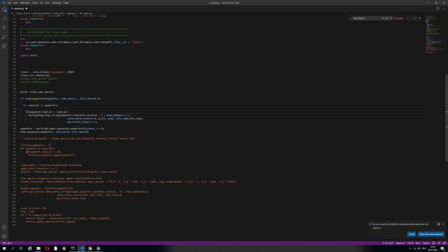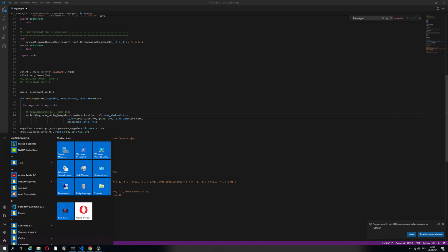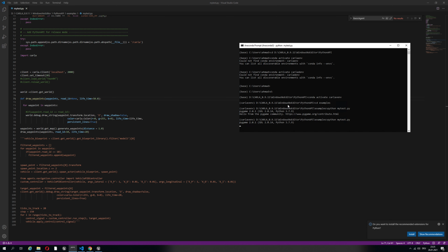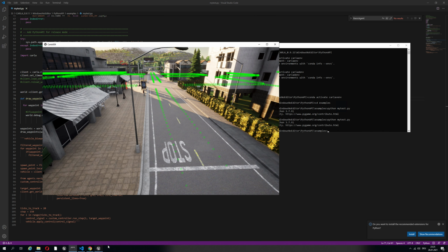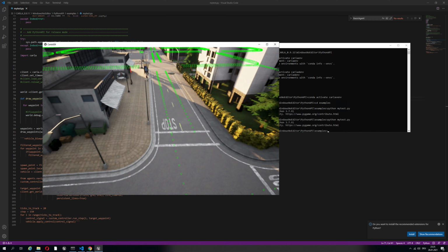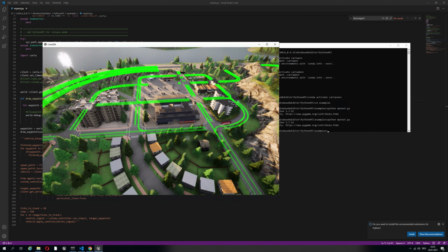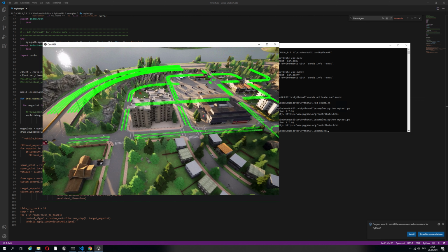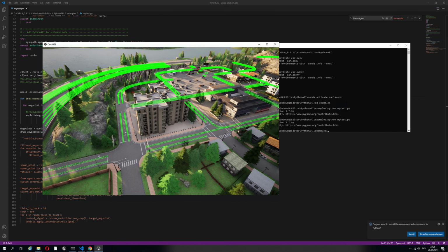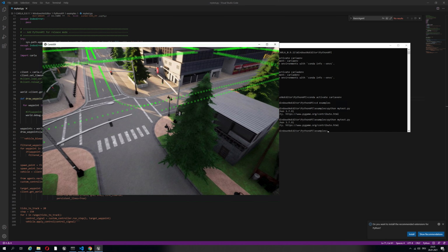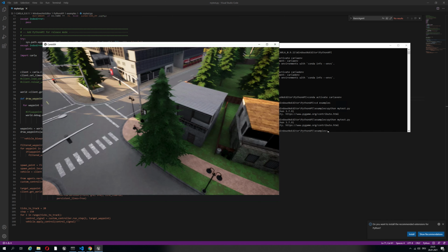And then let's see, for example, that I want to draw all waypoints, not only those of road ID number 10. So I can just comment out this if condition there, then save, then run. And now we see that we have all the waypoints of the simulator. Now it's interesting that there are no waypoints for this road here. Let's see. Probably because it doesn't have lanes.